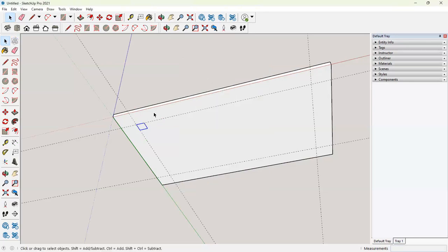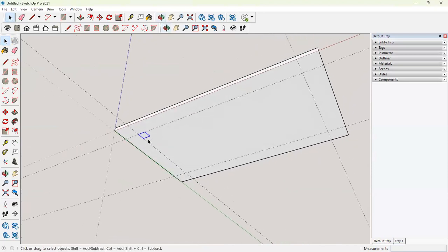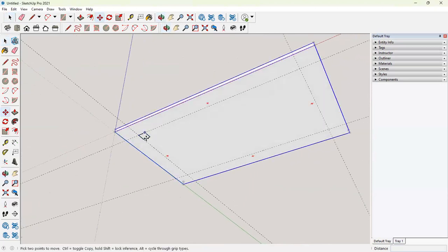Okay. Now again, we need to enter inside this component. Now I'll show you the difference between a group and a component. So let's say we have this leg copied. To copy it, select the move command, select any point, hit Control on your keyboard and leave it. You'll make a copy. Let's put it here. Since we've made it a component, let's put it in all 4 corners actually.